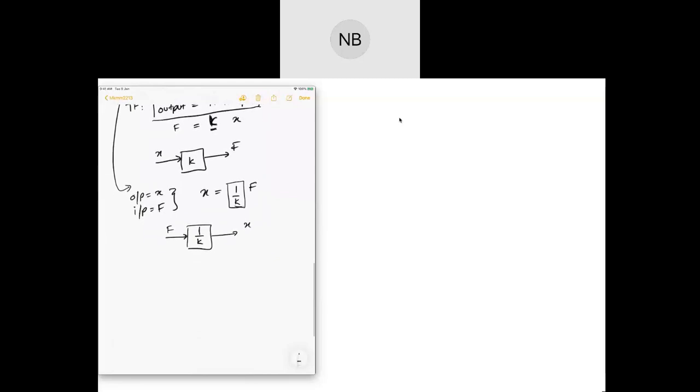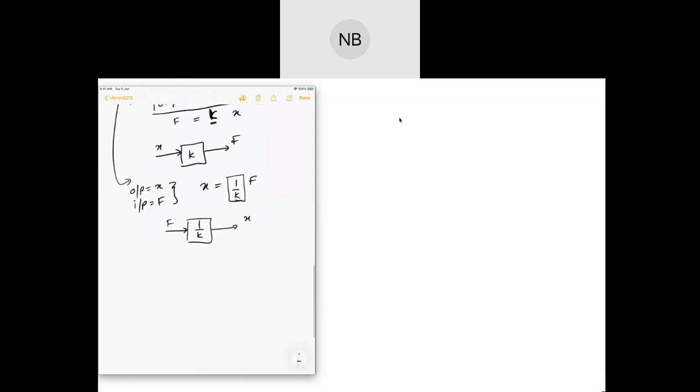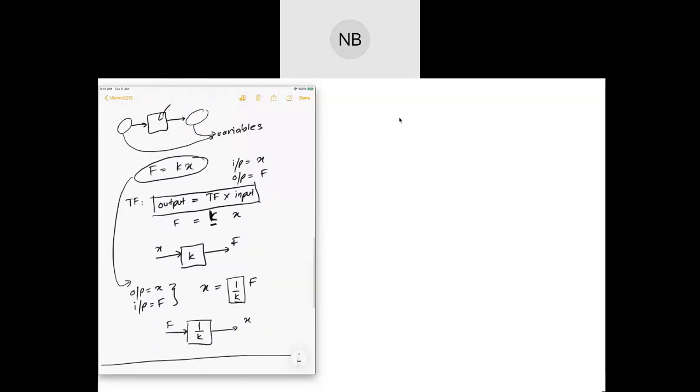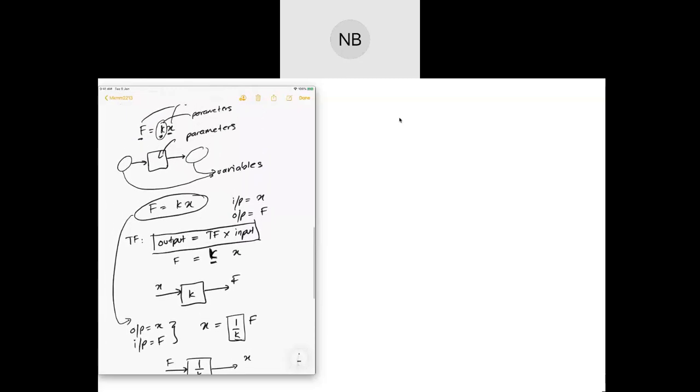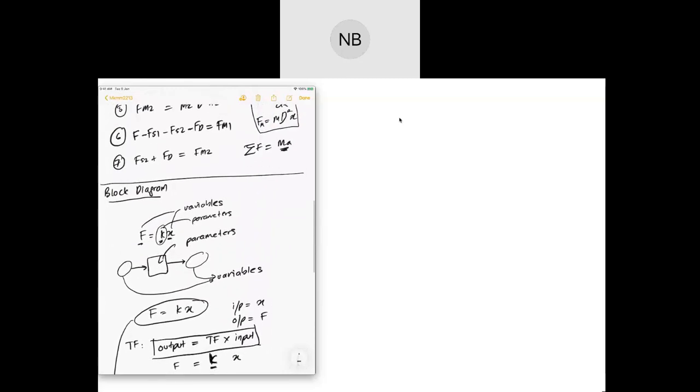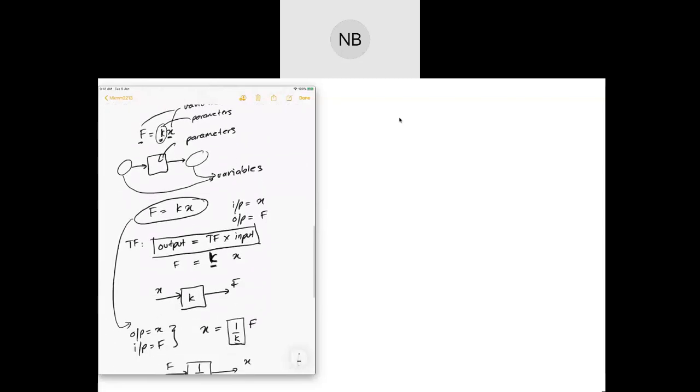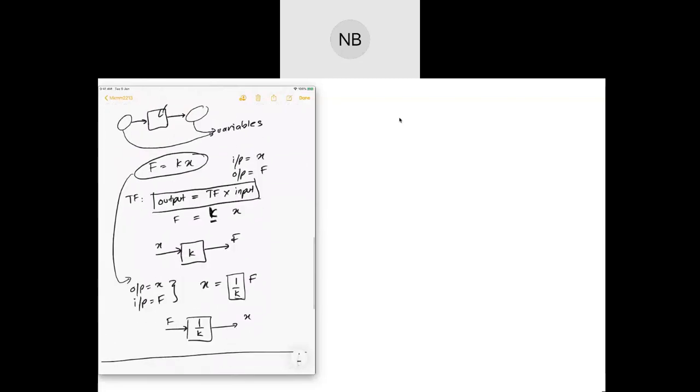All right, so anyway, I'm going to go back to our equation just now, and we're going to draw the block diagram of our suspension system. For your system, you're going to have a summing point also. If you remember, a summing point is where all the signals come in, addition or subtraction of the signals, and then one output goes out from your summing point. I will show you while drawing it later on.